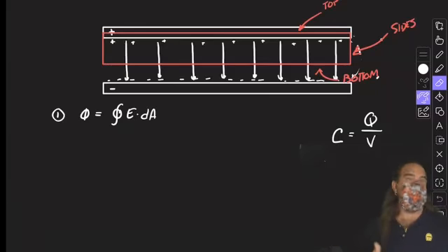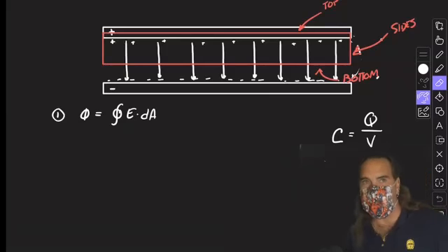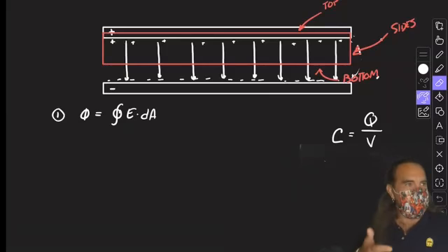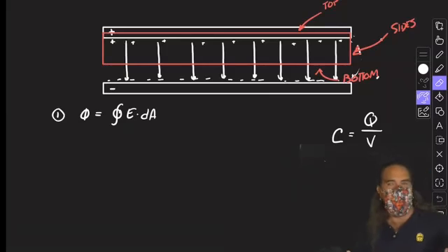That would just tend to increase what the actual capacitance is, because we'll have a little electric field that we're not adding into this. So the electric field will actually be a little bit bigger than what we're calculating, and we're just going to assume that our capacitance is slightly bigger than what we actually calculate. And that's going to be okay. This is how it's done.